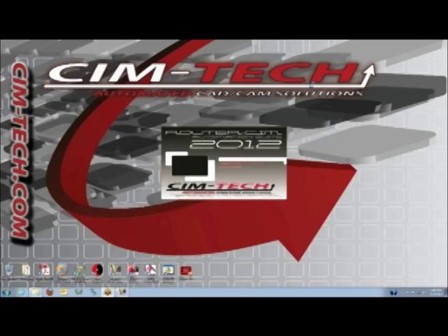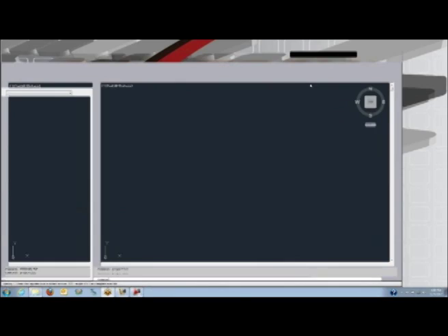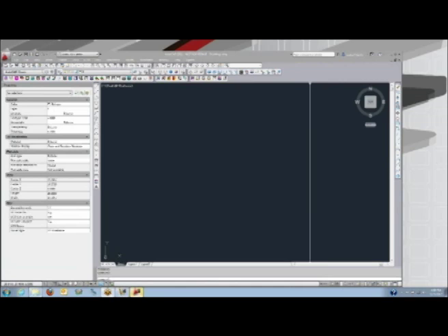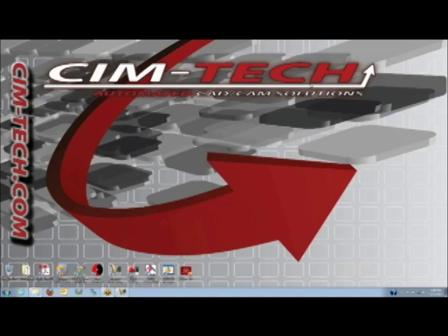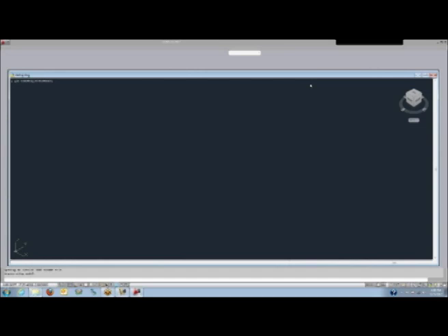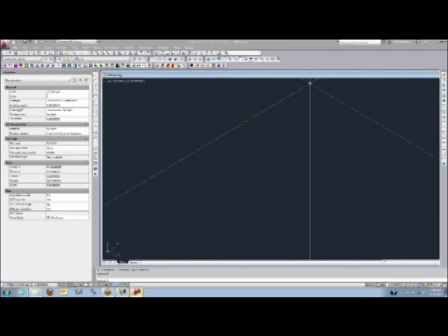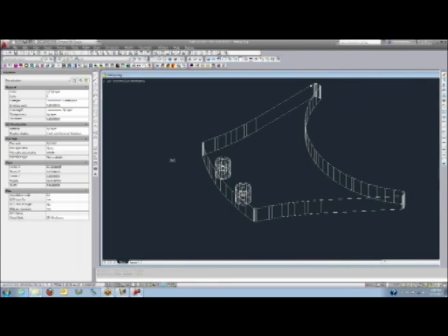All the parts in that assembly were laid flat, feature recognized. A cut list was generated with the part name, the material, and the quantity of each part. So it does see duplicates as well, and it will increase the quantities on those. Then with a simple right click on a CSV file or any cut list, we can import that and run it directly through the AutoCAD automation program.